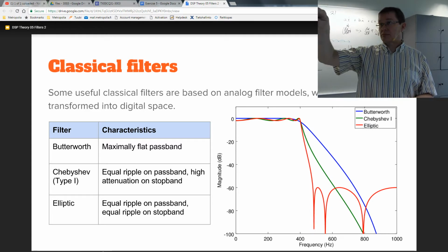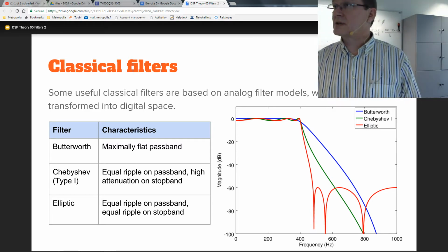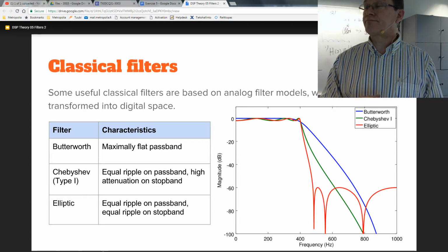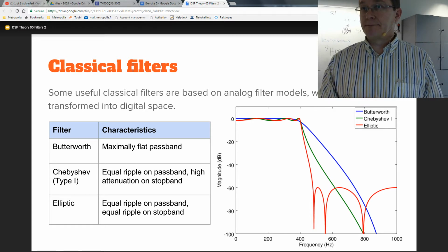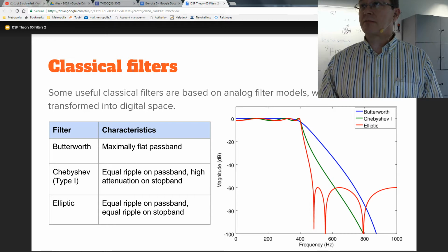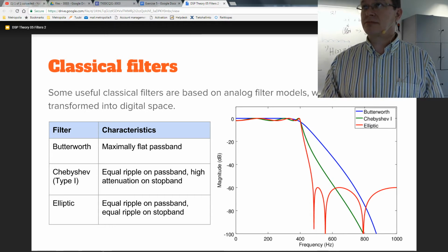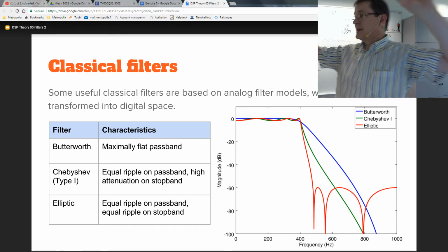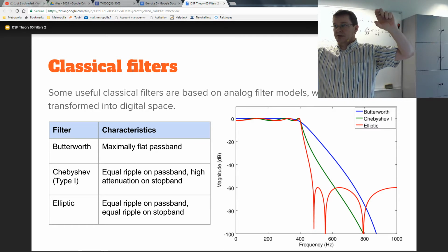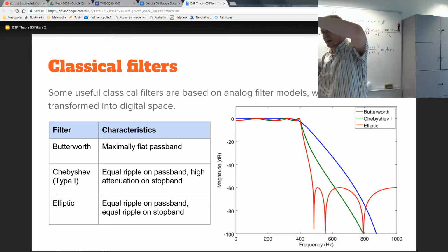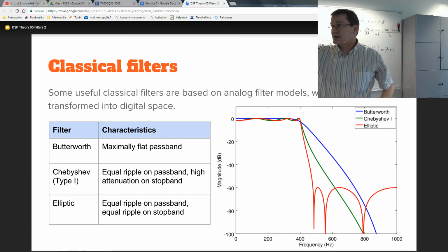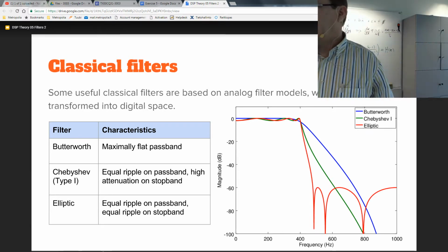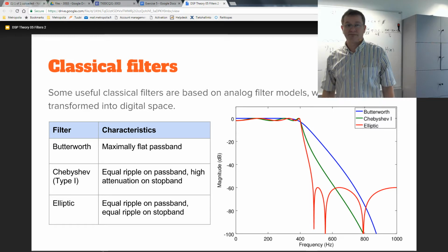Okay, and yeah, that's the history. So what does the equal mean? Equal ripple means a uniform ripple, within say +2 dB on the passband, and then the stopband attenuation level, in that case -60. Yeah, the peaks are at the same level. Yes.